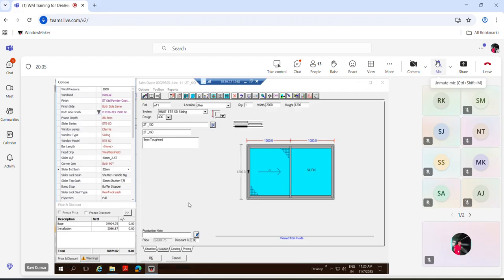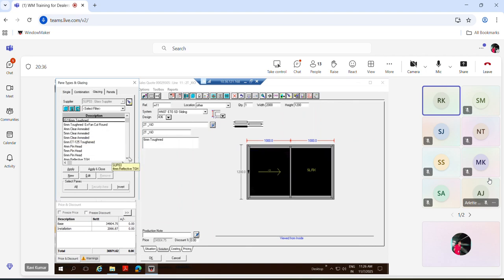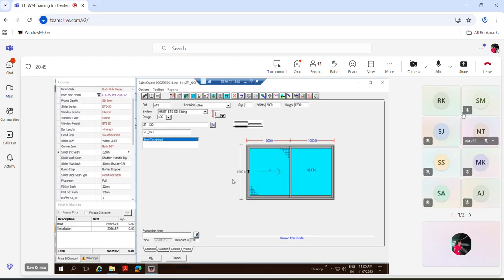Understood. Also, if there is some catalog, if you study or read that, you can understand better. Got it. And if you have to change the glass thickness here, where would you change it? Only two glass thicknesses are available here, right? Yeah, if you have to make it 5 mm, how would you change it? So just click on the glass options. There is one pop-up that will come. Got it. This one for glass. You can select any one from it. Got it. Thanks.